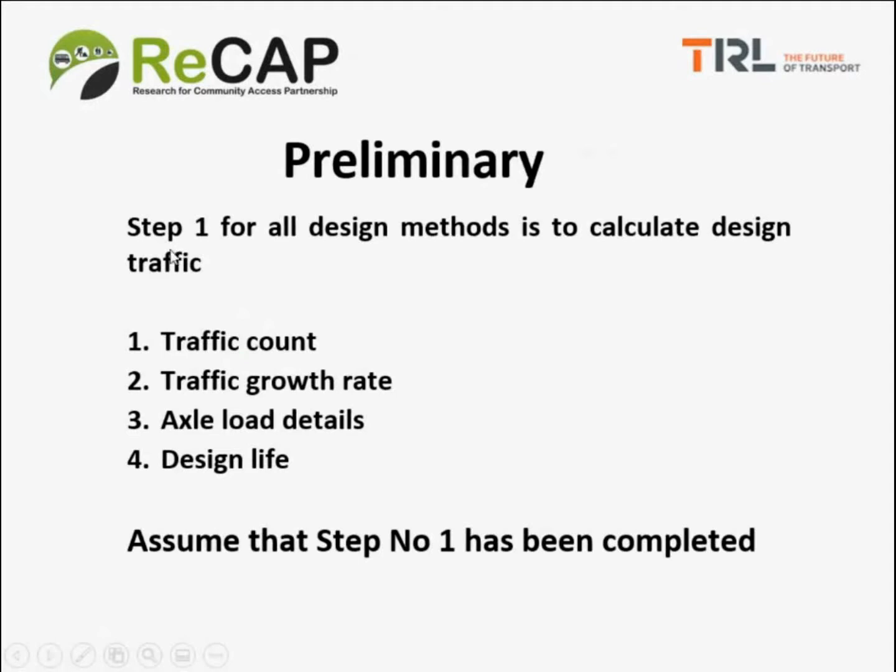Preliminary Step 1 for all design methods is to calculate the design traffic. That requires a traffic count, a knowledge of the traffic growth rate, details of the axle load so the axle load damage can be calculated, and the design life. Normally when we do exercises, we've got half a day or even more, so we would combine this as part of the exercise.